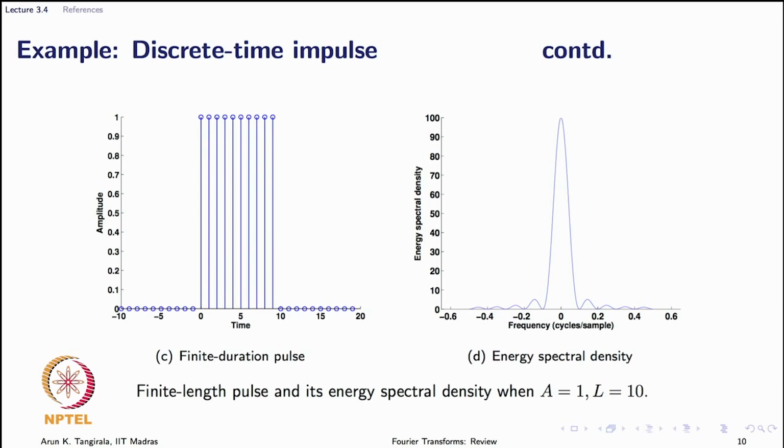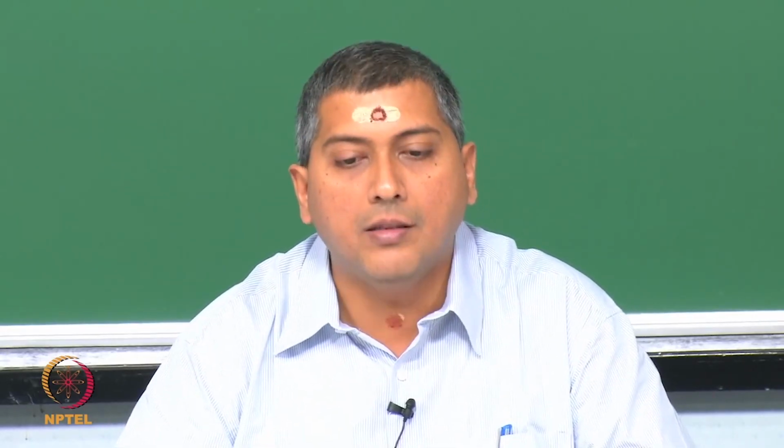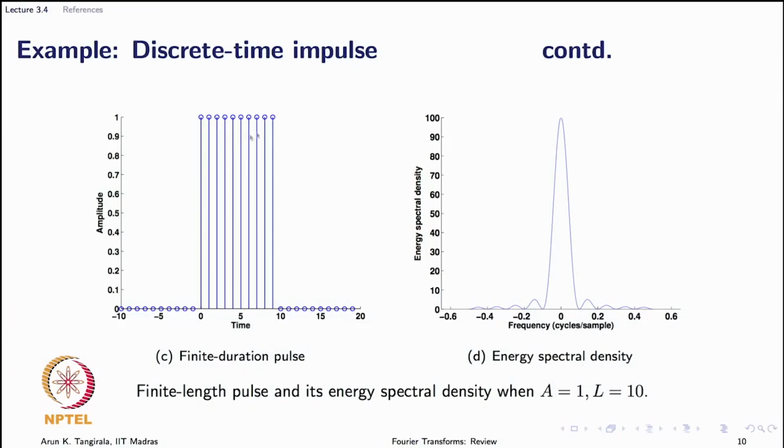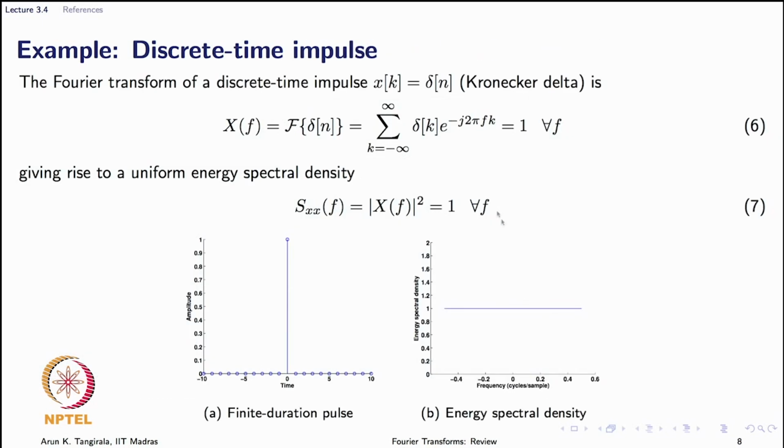Once again you see the same story that we had seen earlier. Now, the signal has a larger duration than the case of the impulse. The duration definitely is finite, unlike the case of the impulse. Naturally, now what has happened is the bandwidth, or the spread of the energy spectral density, has shrunk from being full, from uniform, from being a very large value for the impulse case.